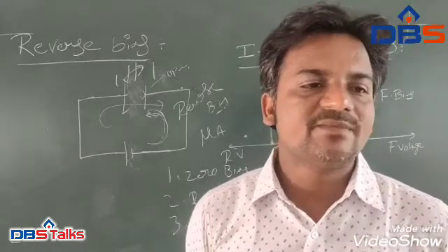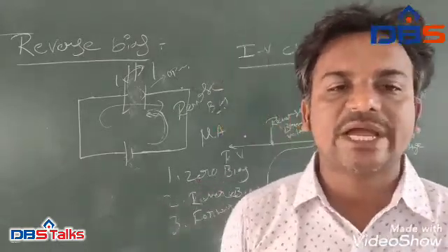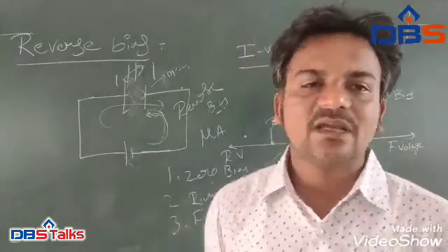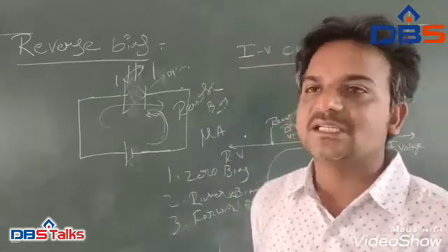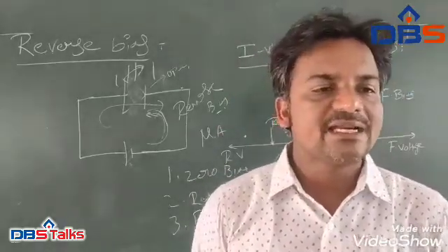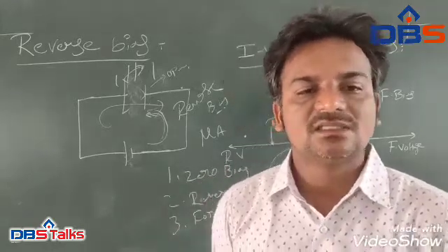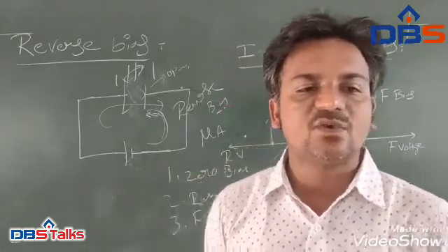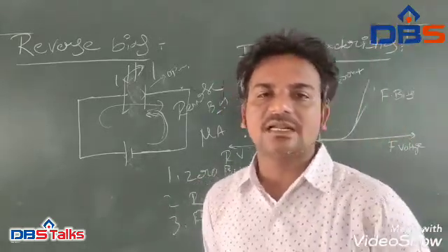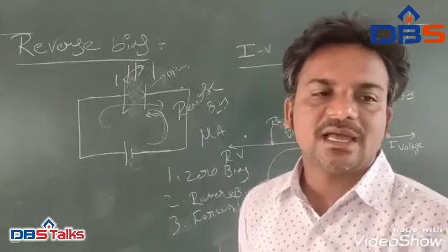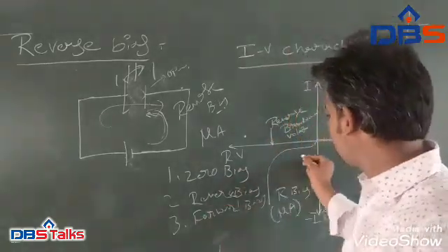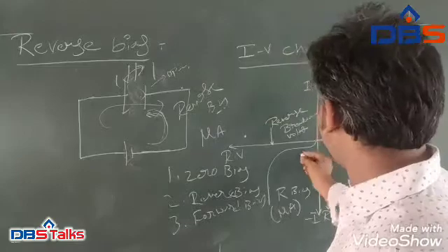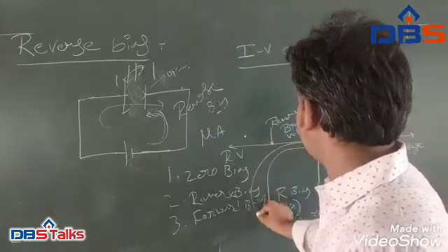So finally, if the reverse bias voltage applied to the diode is increased to a sufficiently high value, it will cause the diode's PN junction to overheat and fail due to the avalanche effect around the junction. This may cause the diode to become shorted and will result in the flow of maximum circuit current, and this is shown as a step downward slope in the reverse static characteristics curve below, within the negative region of the axis.